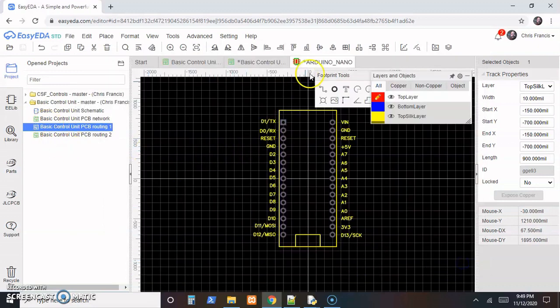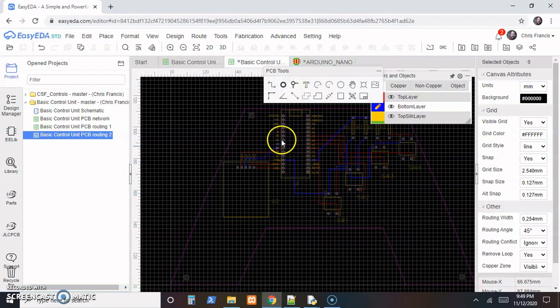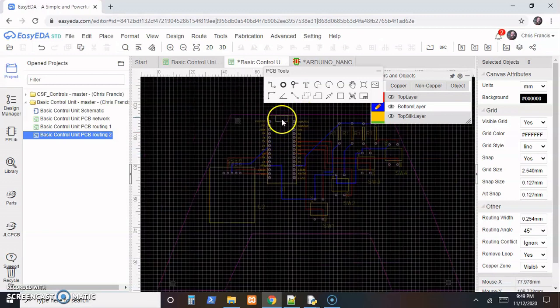If you take that edit option, you get here, and then we can select sections of that footprint, and I've moved that extension up inside the board so that we could still tell where the USB is on the silk screen. And then I made a copy of everything and replaced that Nano with the modified footprint that doesn't have the PCB sticking out beyond it. And while I was at it, I went ahead and straightened up a couple of these lines to make them more parallel.